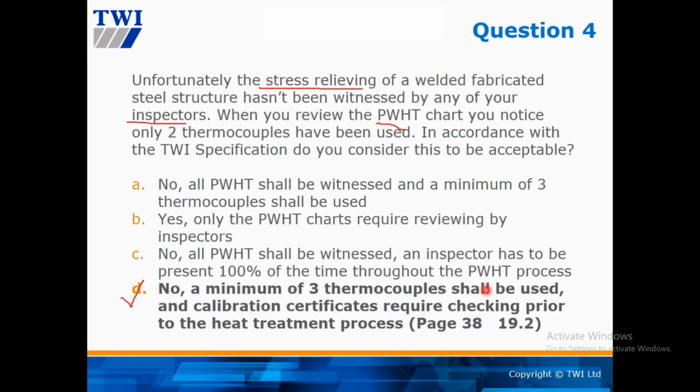Yes. So as an inspector, when you go and visit, you check the procedure, the equipment used, and the calibration certificate. When everything is there, you're not always waiting there. If the heat treatment takes 5-6 hours from start to end, it's not necessary for you to always be there. At the starting point you check the equipment, and then you leave. From time to time, you go and check again. It's not always 100% expected to be in the heat treatment process.